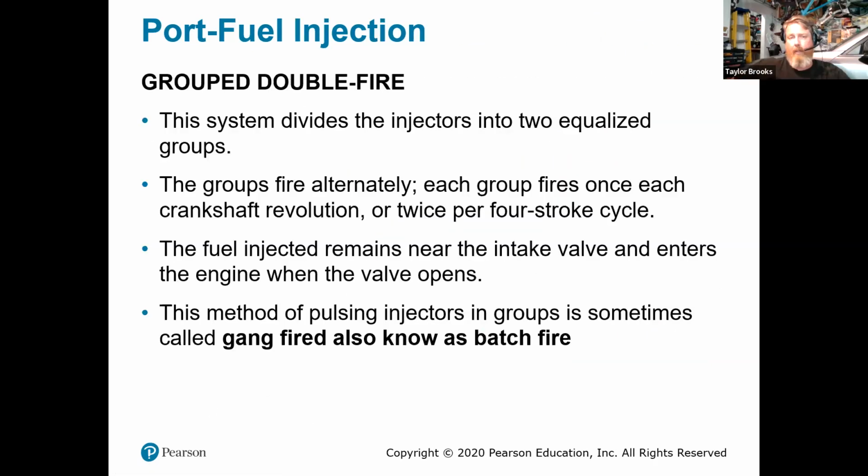Now, one of the ways that we can have our port fuel injectors fire is what's known as group fire. It can be known as gang fire. I've never heard of that except for the publisher saying that. I've always known it as batch fire. And why I've heard it as batch fire is you're going to have batch one, batch two, basically bank one, bank two, and you have a batch of fuel injectors that are going to fire at any particular time.